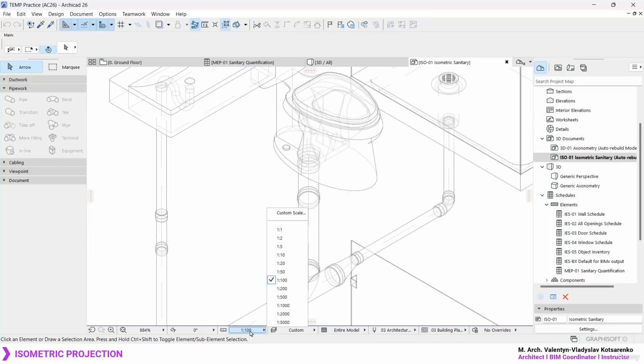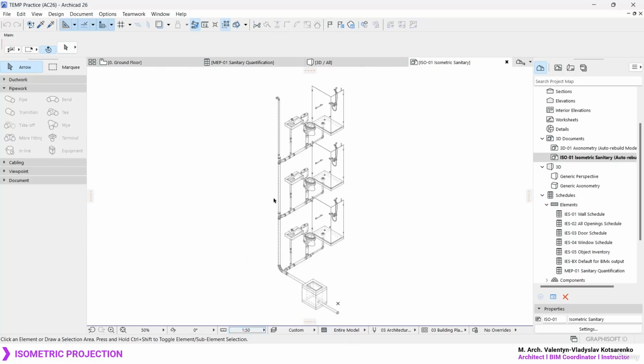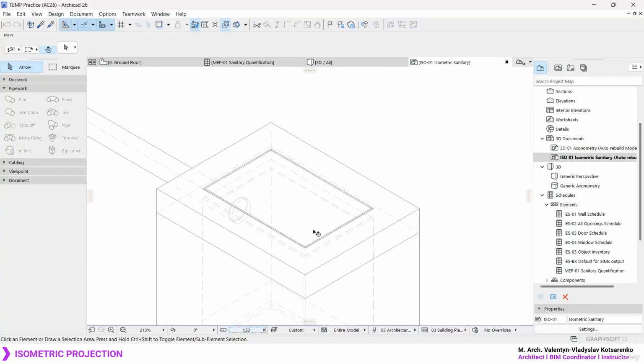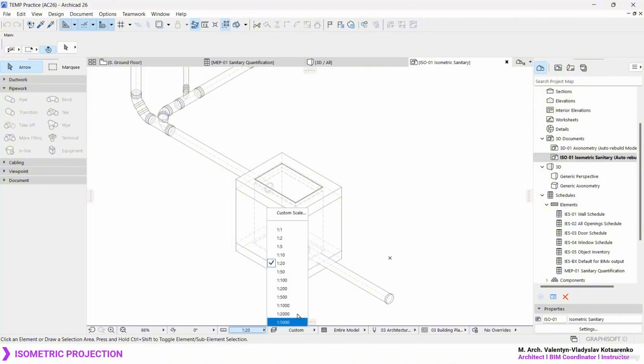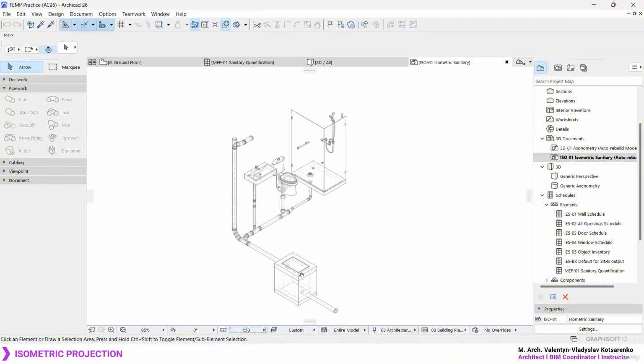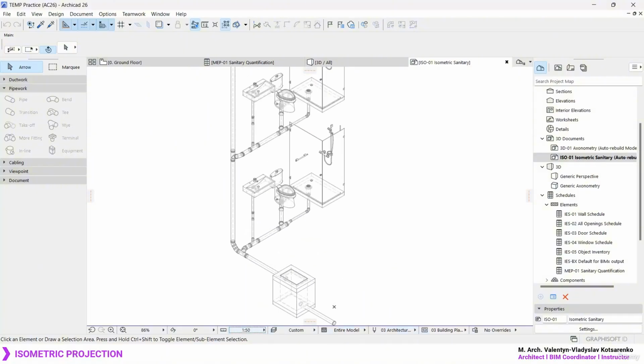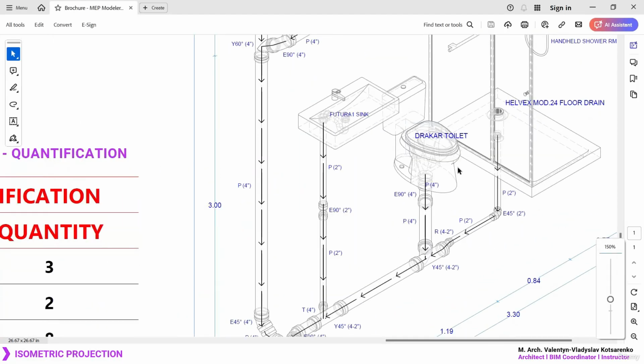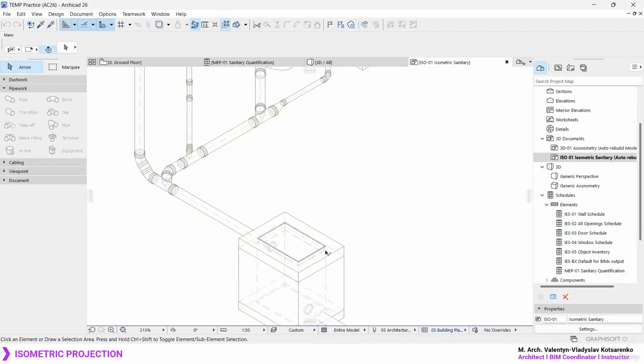Finally, you can go ahead, set maybe the visualization scale or the print scale to something a little bit bigger, such as 1 to 50 or even 1 to 20. I'll leave this decision up to you. For this practical case, I'm going to set it to 1 to 50. If I notice that the tags are still quite big, I can once again adjust the scale. So yeah, it's pretty much looking good.